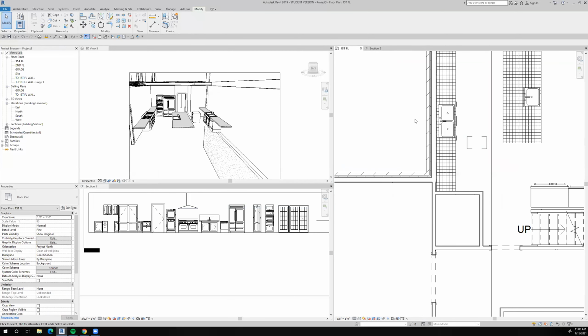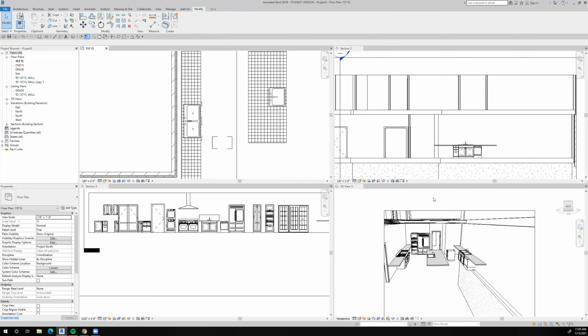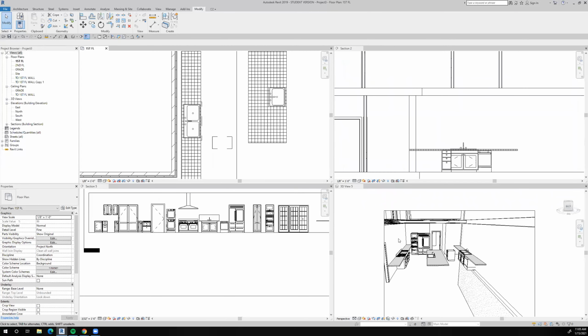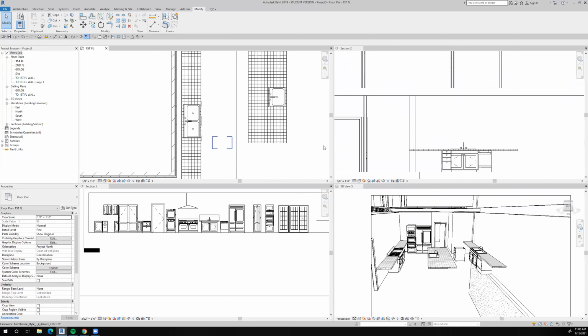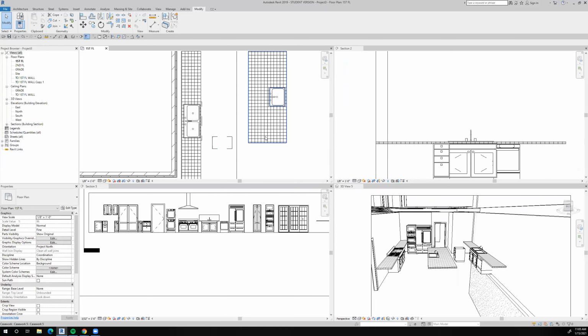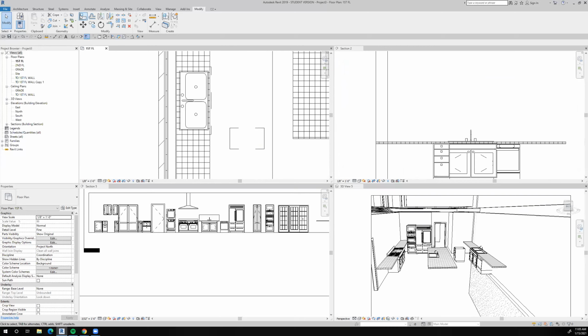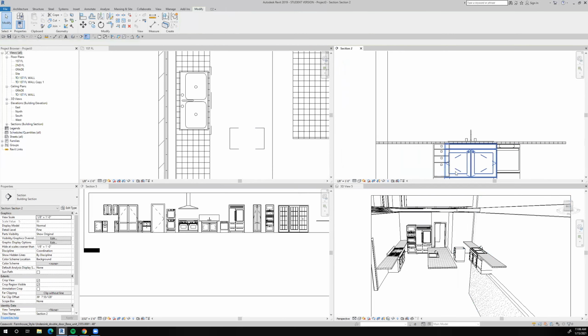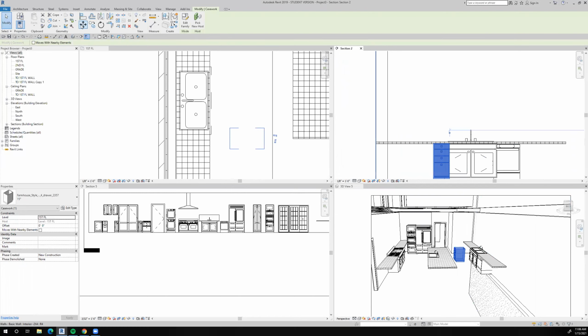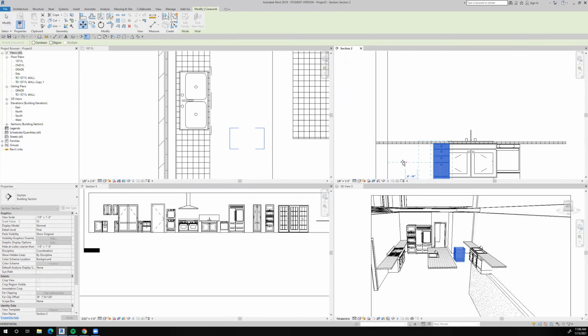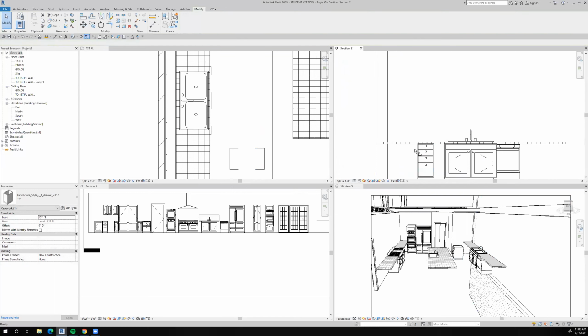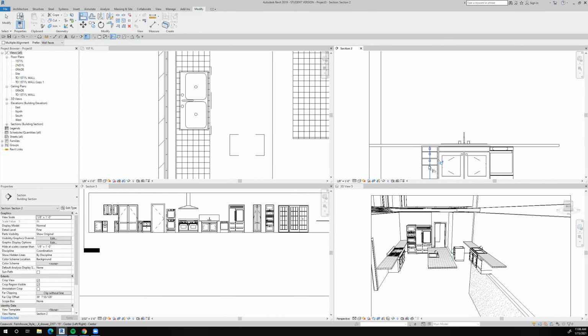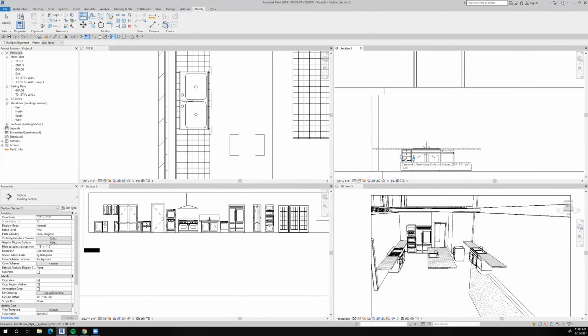And then I'm going to type WT so that I can see this not only in 3D and in plan view, but also as a section. So I can line this guy up. I'm just going to grab this and move it over this way. Grab this sink. The reason I'm moving it over is so I can use the align tool and see the edge that I want to align to. So that looks good.